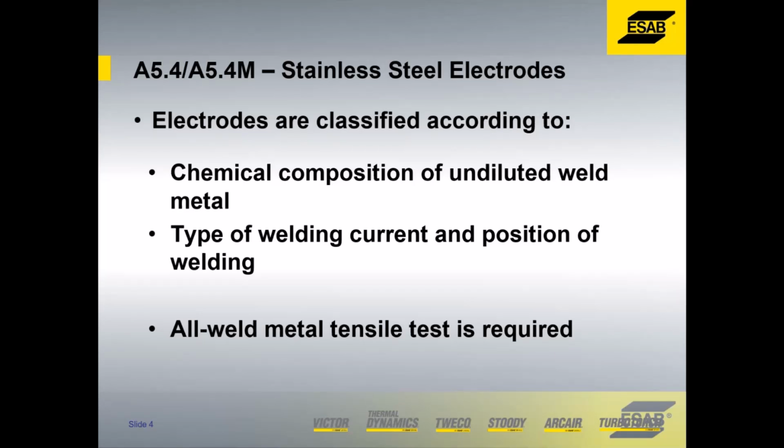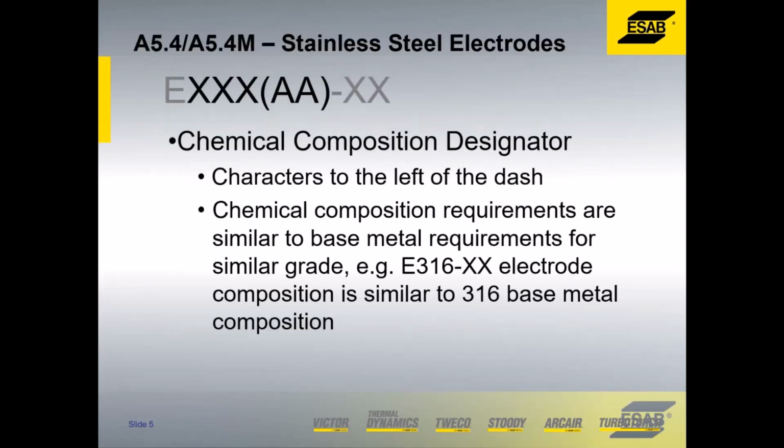That's outside of the scope of AWS and needs to be considered separately, either through different recommendations or corrosion testing. But typically we match the weld metal to at least be as corrosion resistant as the base metal. So you have to be careful with choosing your filler so you can maintain that corrosion resistance.